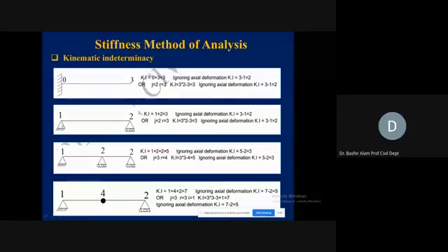And here only one rotation we have. So it means 1 plus 2, it is 3 degrees indeterminate. So simply by observation, you can write 1 is coming from here, 2 coming from here. This is 3 degrees indeterminate. Ignoring the axial effects, again, one member you need to subtract. So this is becoming 2 degrees indeterminate.